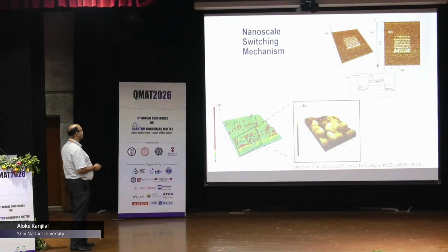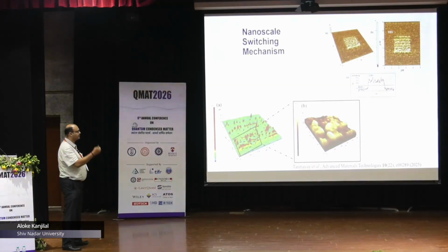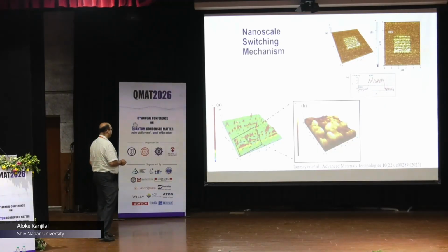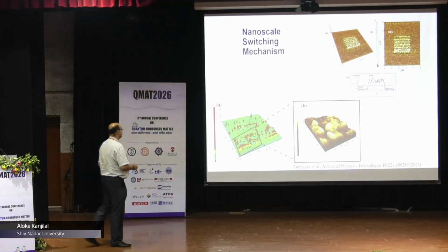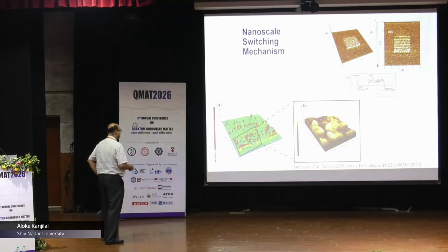And how is this working? We magnified it, and when we put it in the 3D mode, you can see that these kinds of spikes are formed. These spikes are nothing but the current coming up, and not everywhere is like this. Some regions have it, and that confirms this is the region where the conducting filaments are formed. If you keep on doing this, sometimes we found that gradually these filaments start mingling together and then make a channel.